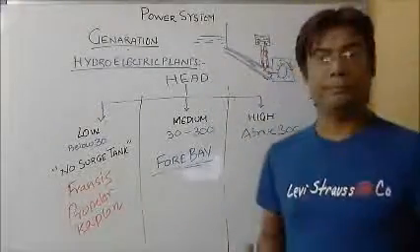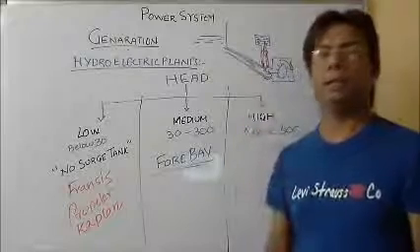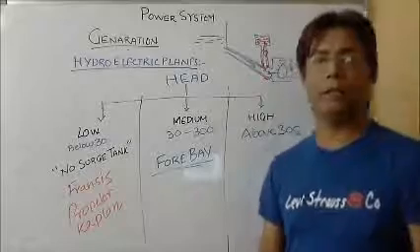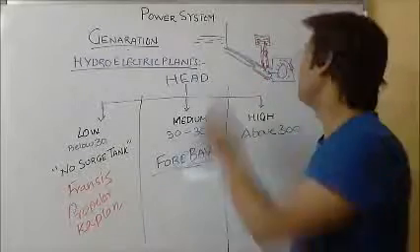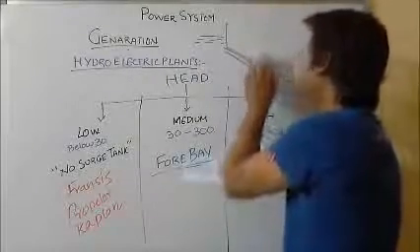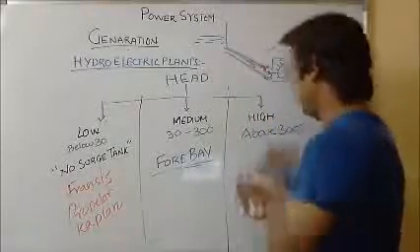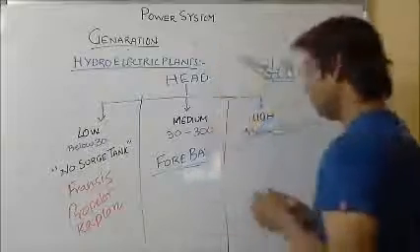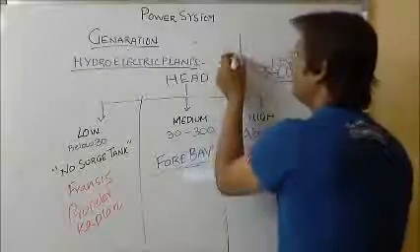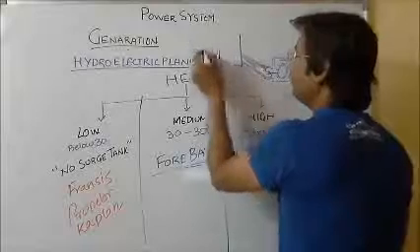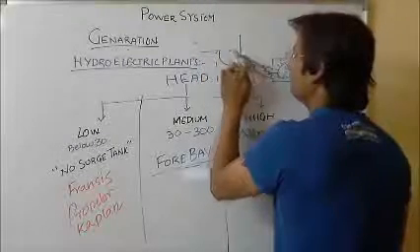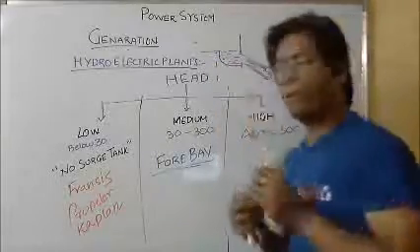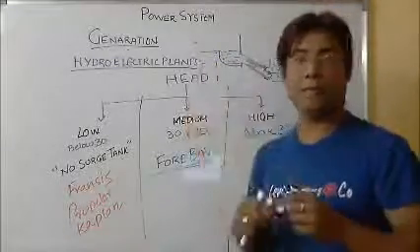What is a forebay now? As we have seen, there is a surge tank required during the load reduction and load increase, the acceptance period. So rather than using this, I can have an arrangement here also: this is my dam, and before that this is my head. I have a tank over here. This is called a forebay, which is just before the intake of my penstock.